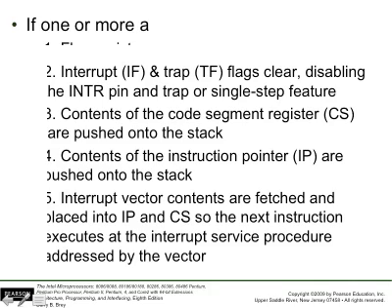It'll check if the interrupt flag and trap flag are asserted or not. If they are, we're going to clear them. Then also we're going to disable the interrupt pin. This is to go into the single step mode. Because in a single step mode, the processor is waiting there. It does not have the capability to respond to additional hardware interrupts. So that's why it will disable that.